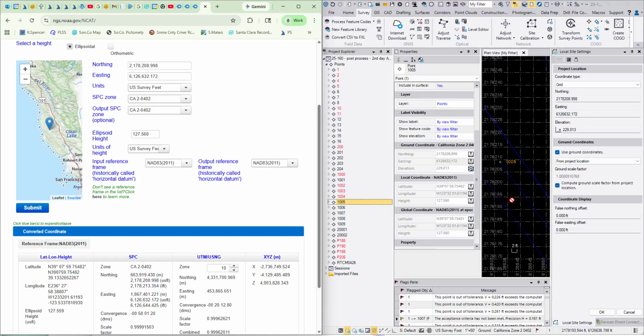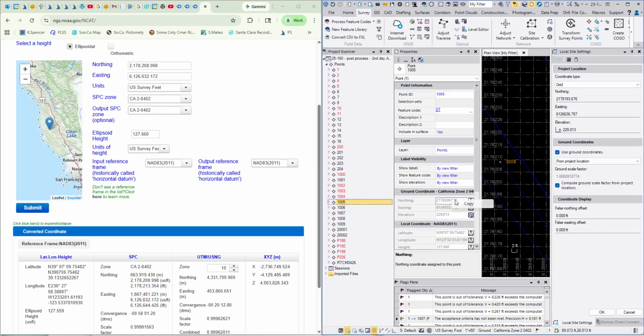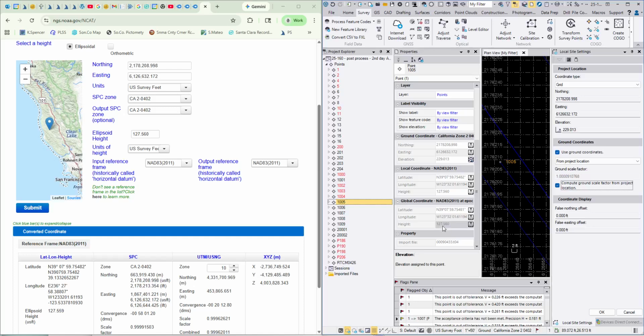just know that in TBC, obviously when you do this, you can click grid here and like I said, you just click the point and it'll calculate from your orthometric height. So let's see, if we were going to copy it right from this point here. Copy. Let's copy there, 9107768. But just know when you put it into the NGS, put in your ellipsoid height, and you can get that from here. All right.